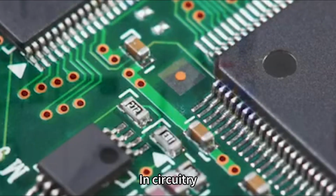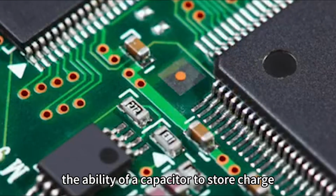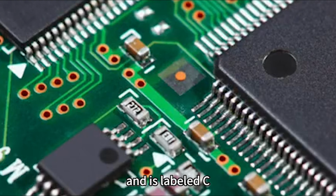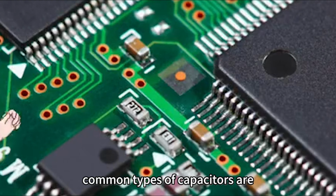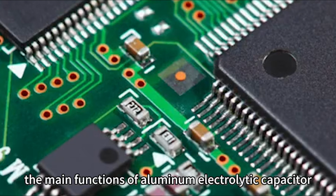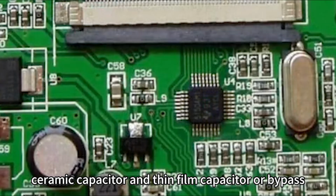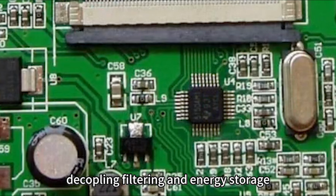In circuitry, the ability of a capacitor to store charge at a given voltage is called capacitance and is labeled C. Common types of capacitors are aluminum electrolytic capacitor, tantalum polymer capacitor, ceramic capacitor and thin film capacitor. The main functions are bypass, decoupling, filtering and energy storage.